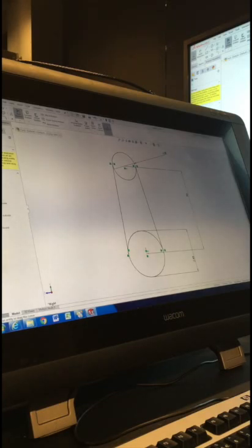Power trim is the one you'll use 90% of the time. The way it works is you click and you can drag your cursor around, and the shape that you create, it will trim any line it crosses over to the nearest points. If you keep going, you can remove your whole sketch, but then you can just press Control Z and undo. So undo and redo work to a certain extent in Solidworks.